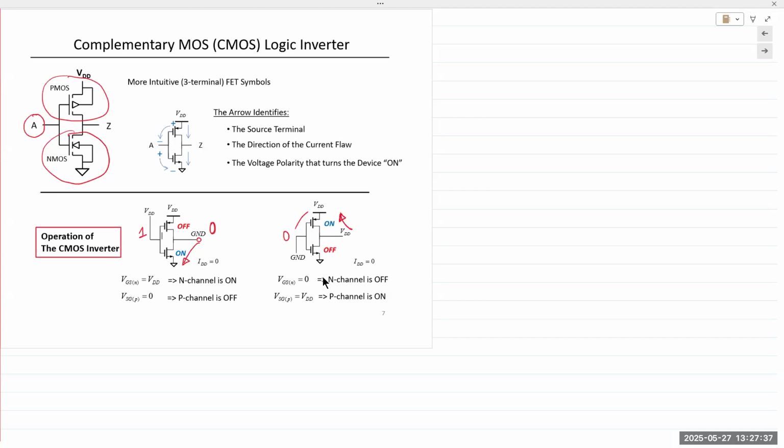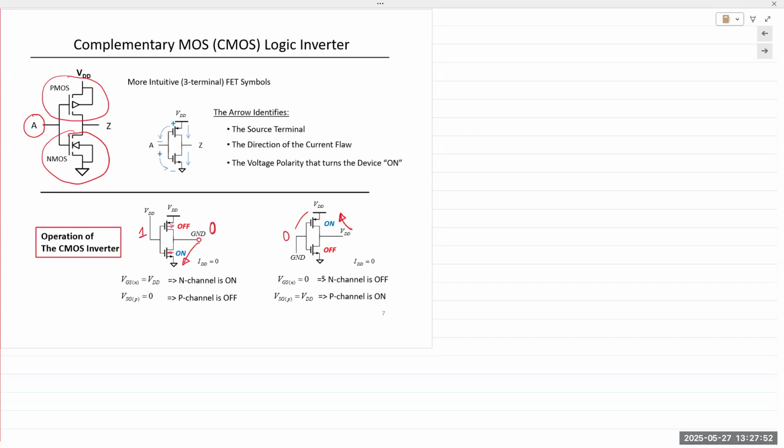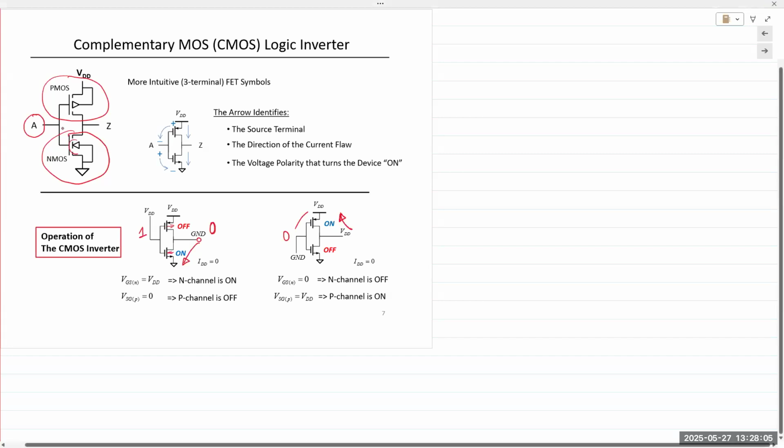So the comment being made was there is no body connection shown inside these MOSFETs. And if it was shown, it goes like this. For PMOS, the body arrow points out. NMOS, the body arrow points in. Just makes it too congested and crowded. No, it's right here. It's right there above.